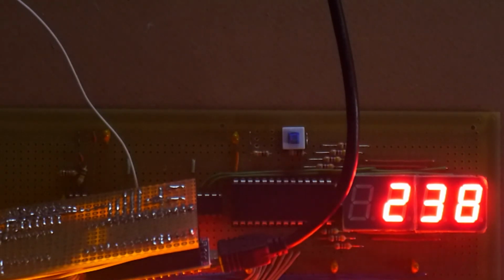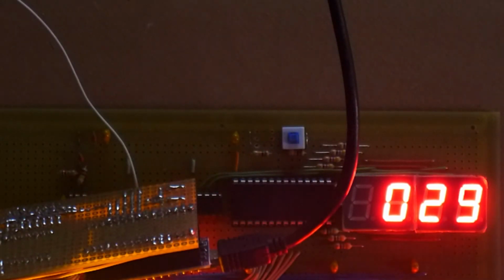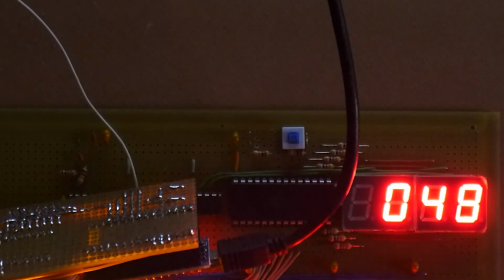And so we can see that the display is working pretty well. And also I have programmed the two's complement with the push of this button. And if we push here, you will see that as it comes to the 127, it will jump to minus 128, which is what we would expect for a binary encoded two's complement number.